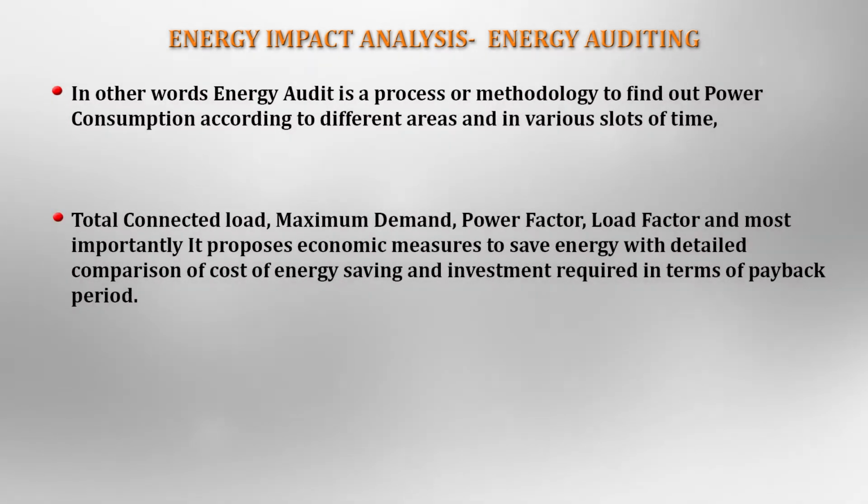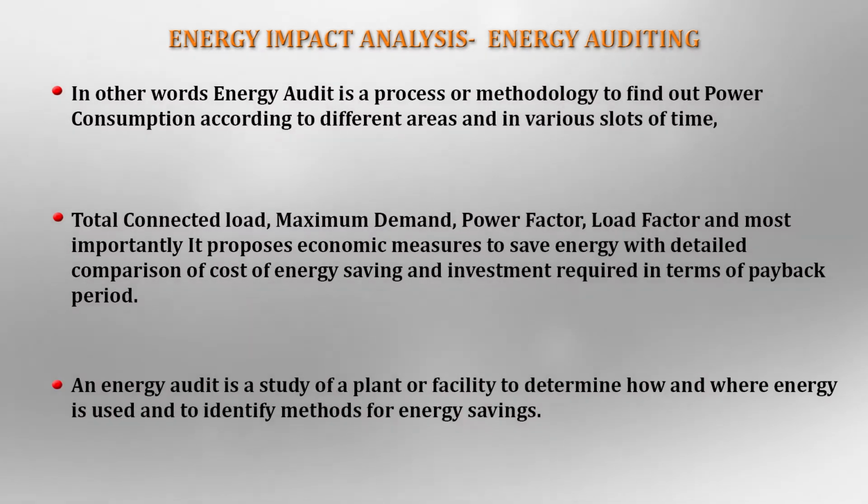Total connected load, maximum demand, power factor, load factor, and most importantly, it proposes economic measures to save energy and a detailed comparison of cost of energy saving and investment required in terms of payback period. An energy audit is a study of a plant or facility to determine how and where energy is used and to identify methods for energy saving.